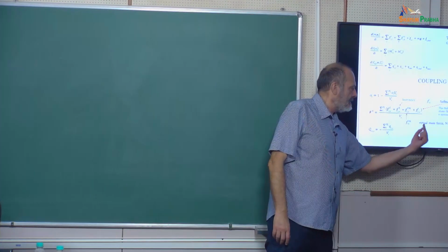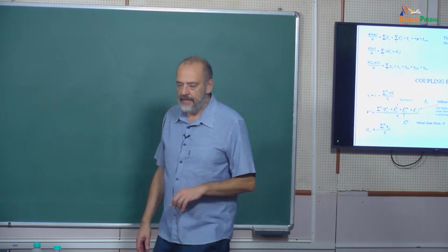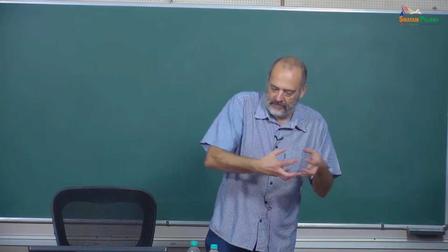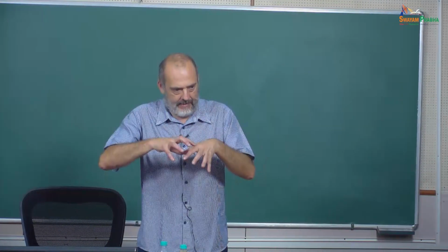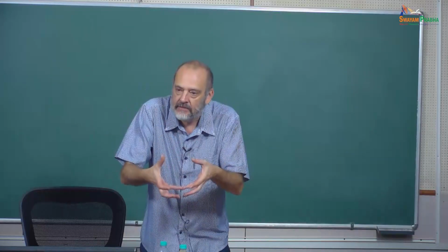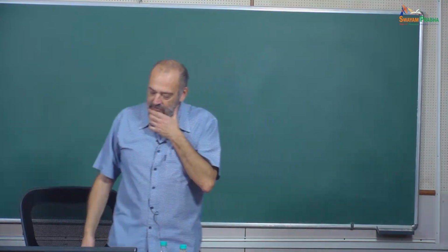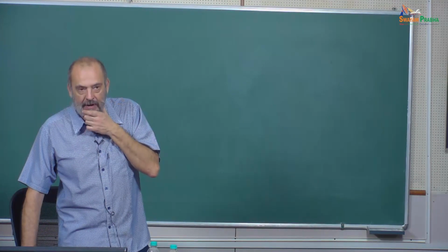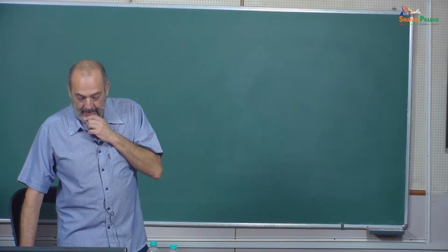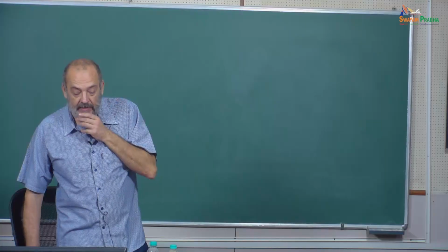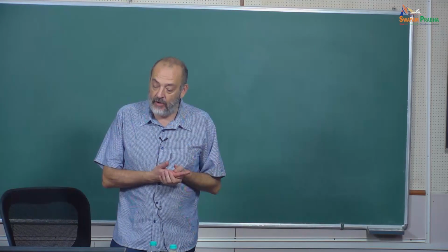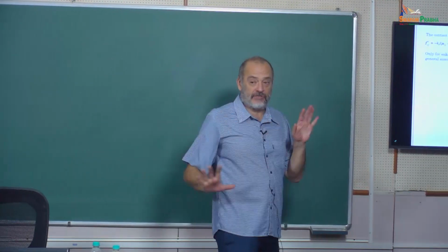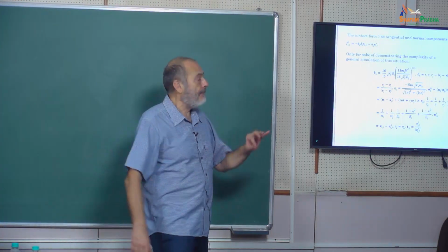And what is also interesting is that there is a virtual mass force, that is the force of the parcels together acting on the continuum. Because the dispersed flow is adding mass to the system locally. And this is something that we need to consider inside the so-called virtual mass force. Things are becoming really very complex because, for example, the contact force has a tangential and normal component, and then look at this. There are pages and pages of equations. So I stop here, but only to make you understand it.